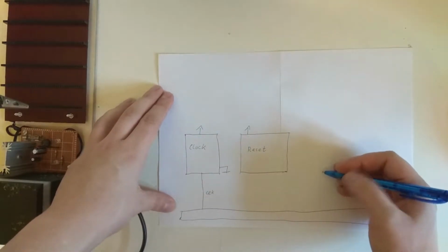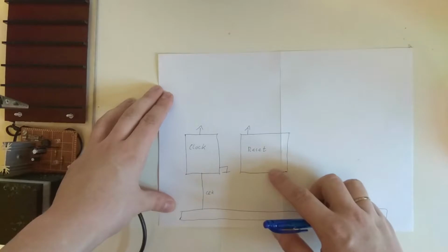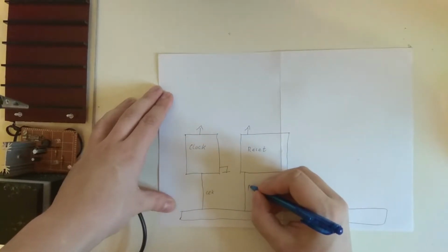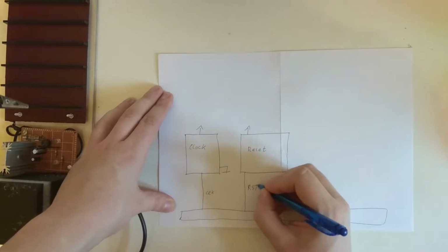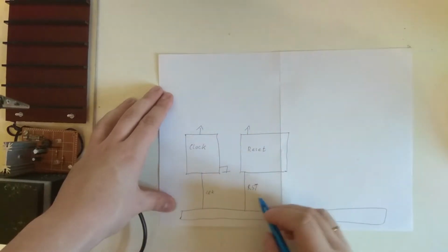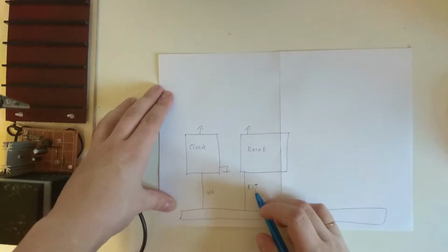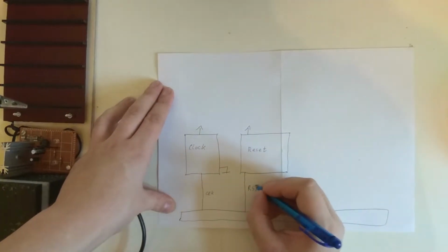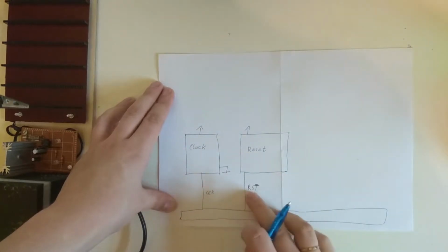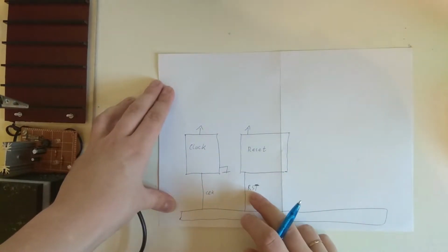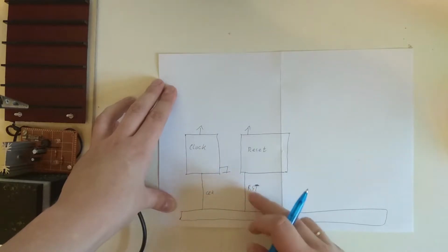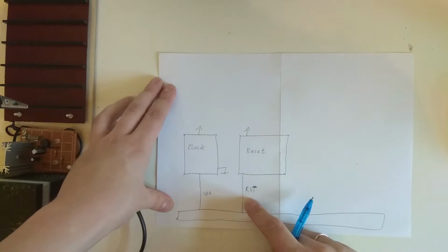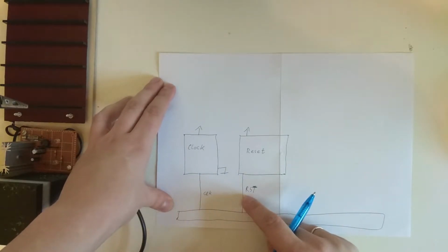So that means I want the reset line that's also here on the bus. I want this to be low when the computer starts up, and after the power supply stabilizes, I want this to go high and basically reset everything until everything is in a known stable condition.